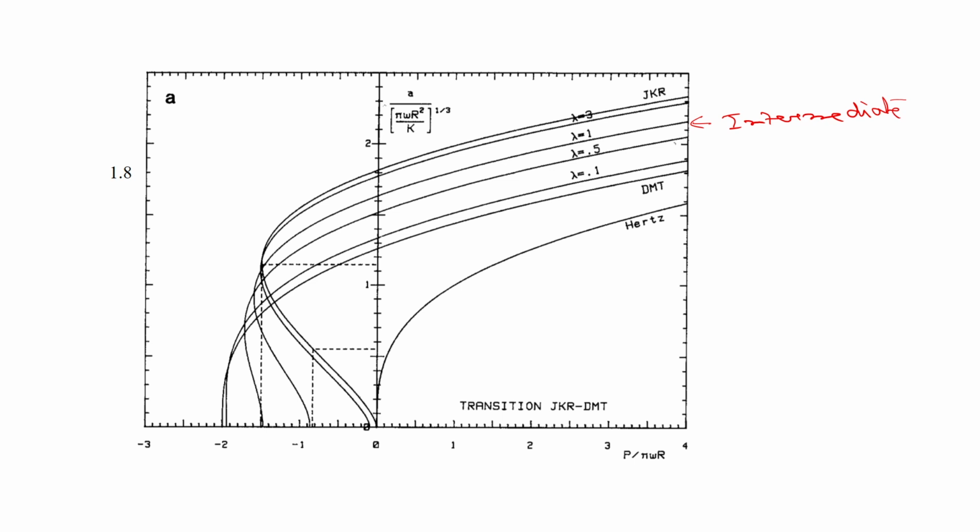For the pull off load calculation, you see that as the load is being decreased, from compressive to here it is compressive, and this side it is pull off, negative load. So, negative load means pulled off. Contact area decreases, and there is a kind of instability here. Now, for lambda equal to 1 it goes to somewhere here. So, the pull off load will be when the load decreases to this negative value, okay. These portions will not be attained in experiments.